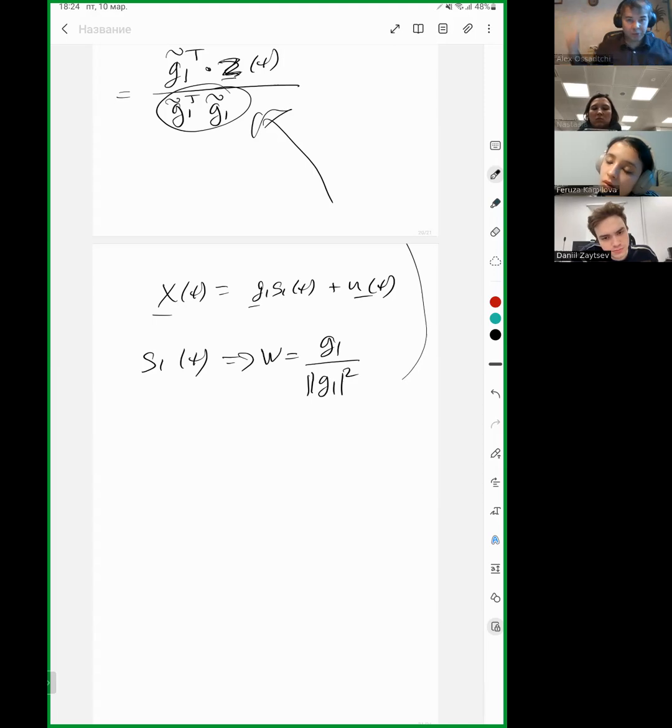Okay, because the best thing you can do, once you distribute it everywhere, is simply to look in this direction. You maximize the cosine of the angle between you and the source. And that's basically the explanation of how the beamformer works. There's no magic. It's all trivial. It's all second order stuff. It very often boils down to very natural explanations.